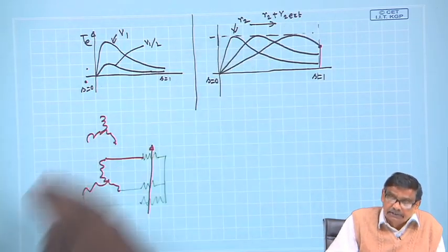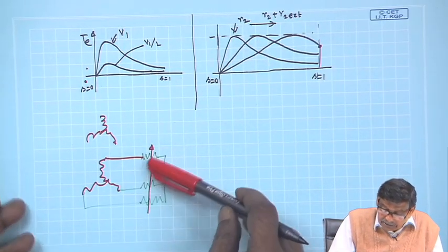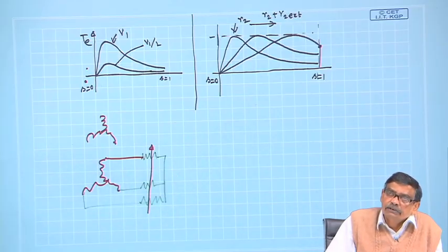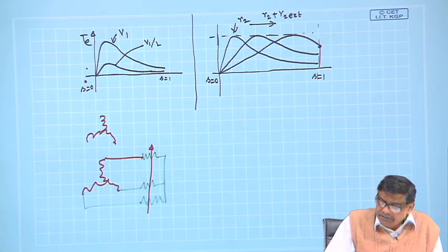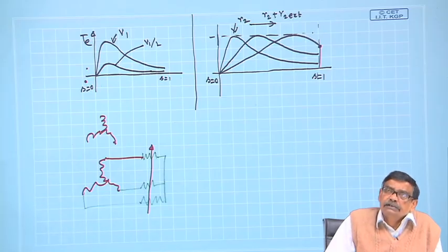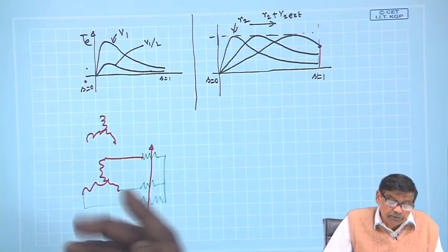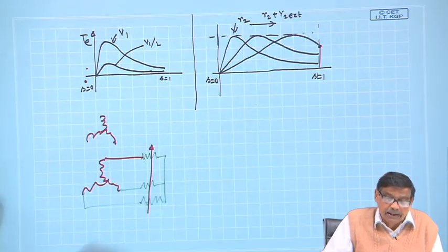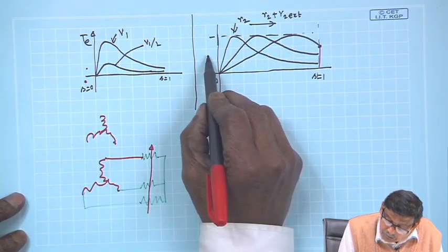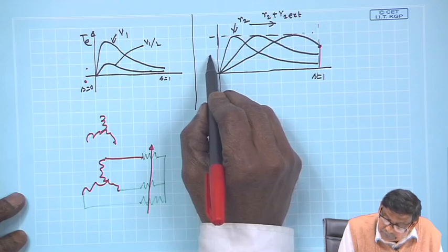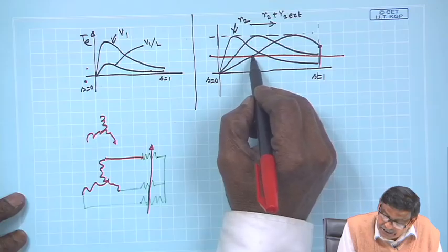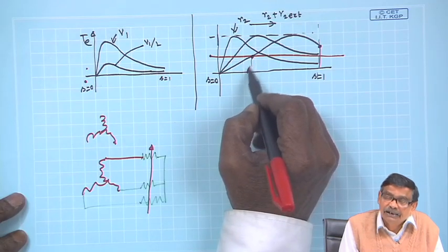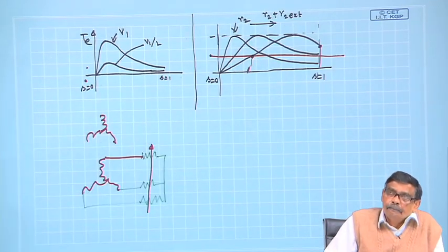with inherent rotor resistance, because if you keep this rotor resistance in the circuit, there will be additional copper losses, and additional copper losses mean the efficiency of the motor will be reduced, and the machine will be running at a much lower RPM, because if this is the load torque, if you keep this resistance, it will run at this higher value of slip and things like that.